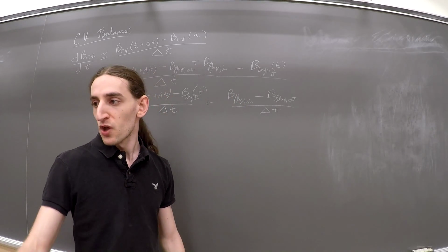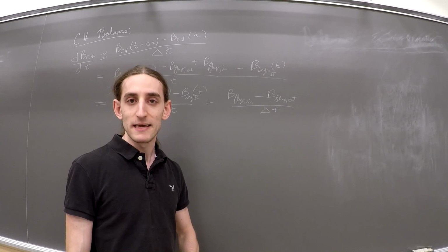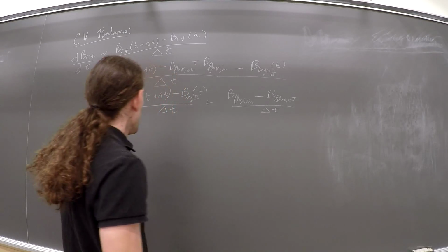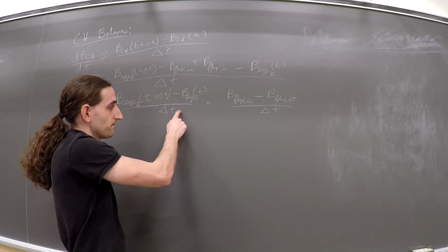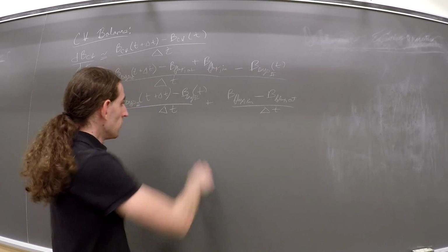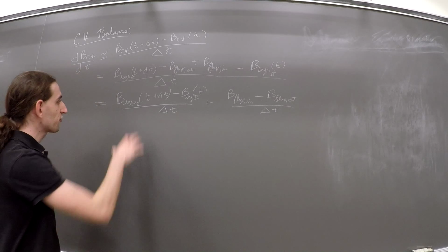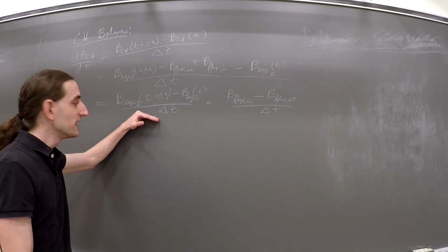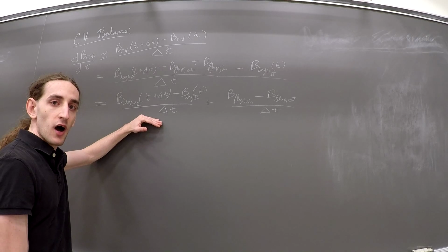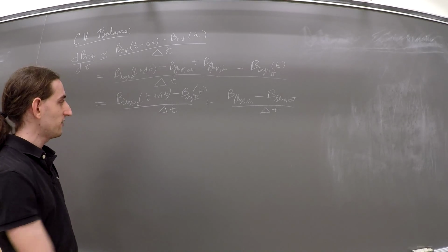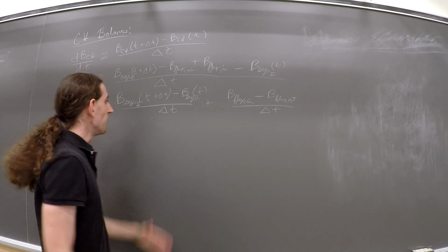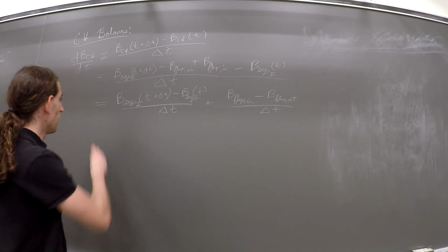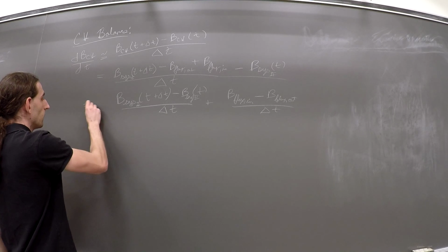They're just B rho A V delta t. So our delta t's are going to cancel out, which is pretty nice. And then we can do some nice stuff with this. So let's focus first on this term here. Our system term looks very familiar. It should look familiar to you because it looks like the definition of a derivative, right? If we take the limit as delta t becomes very small, then that's just the derivative of the extensive property in system 2.